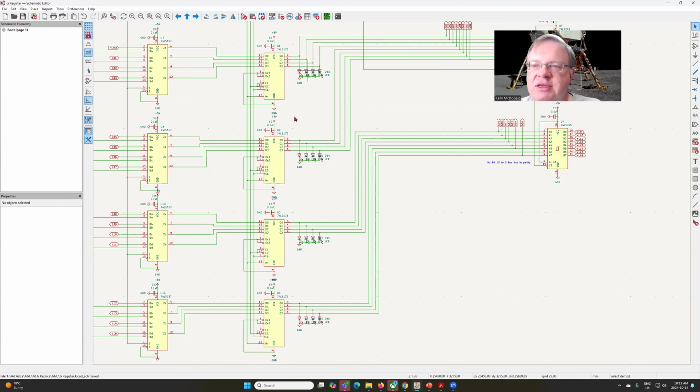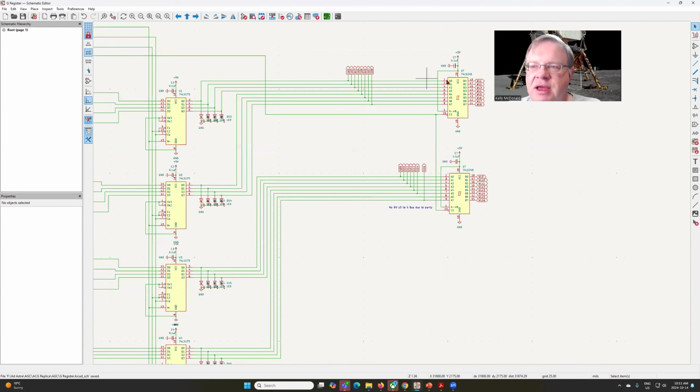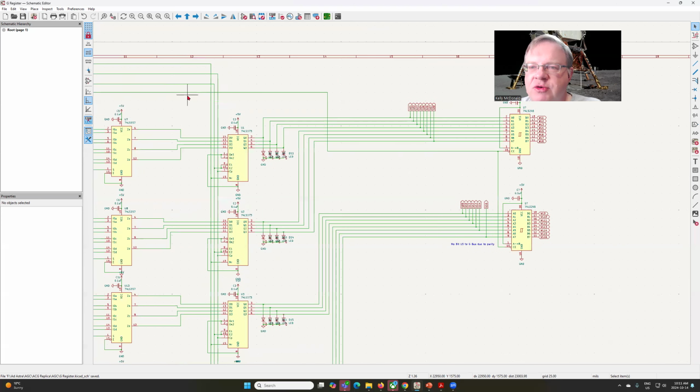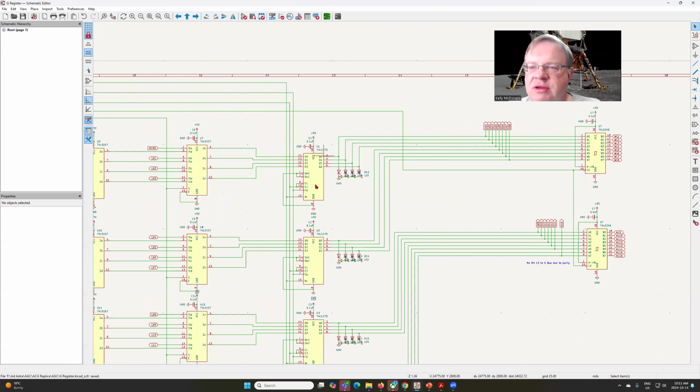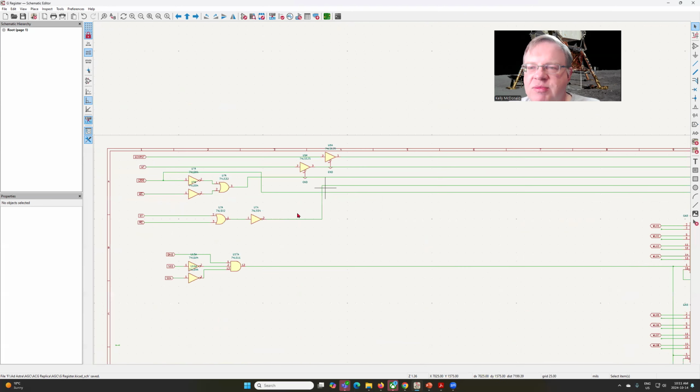We've got our LEDs so we can see what the contents are. And then to write out back onto the write lines, we have a pair of 74LS245 octal transceivers. The control circuit or logic for these two is again pretty straightforward compared to what we've seen before.